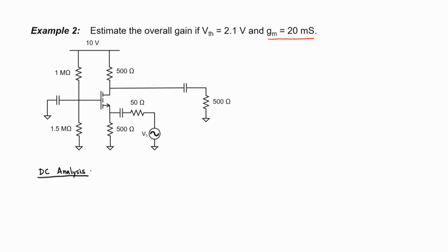saturation region. Let's find our gate voltage, and we typically don't have much leakage into that gate, so we don't have to worry about the gate current being negligible the same way we would have to worry about the base current being negligible or not in a bipolar transistor. That means we can use large resistors in general when we're biasing the gate of a MOSFET. We have a simple voltage divider here. It's just our power supply times the fraction set up by these large resistors. The ratio gives us 6 volts.